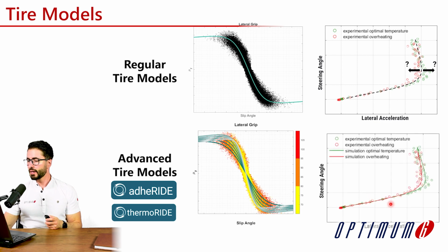different temperatures. And for the same plot, if we give boundary conditions that are warmer and the tire is overheating, we'll see this decrease in lateral acceleration, while when we are at the ideal operating window of the tire, we can see higher grip. Since we can now take temperature into account, we can perform advanced simulation analysis, trying to, for example, prepare a qualifying lap or understand how to manage temperature over the race. I'll show you some really interesting case studies later on in the video.